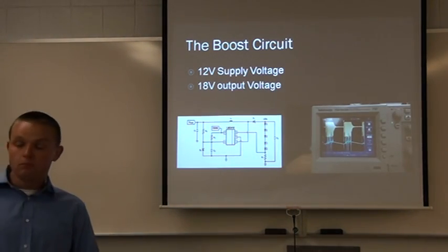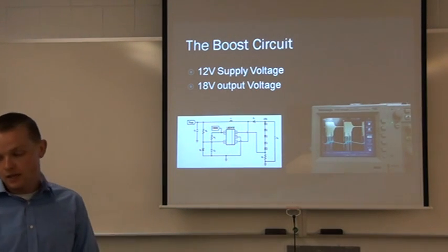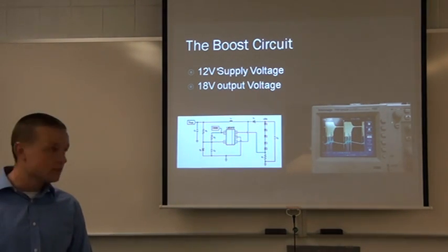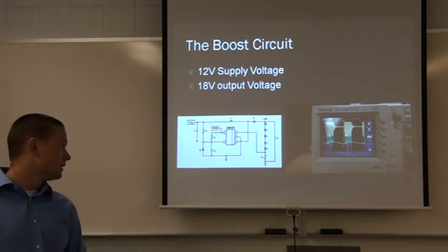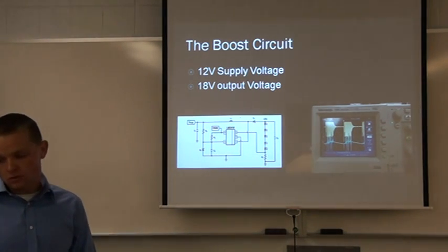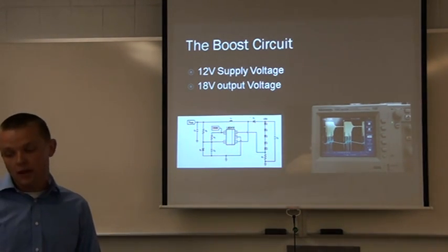Here's the boost circuit that I created. I'm using a 12 volt input supply. That's what your car typically has. And because I have the 9 LEDs in series at 2.2 volts, it's going to have roughly an 18 volt output.